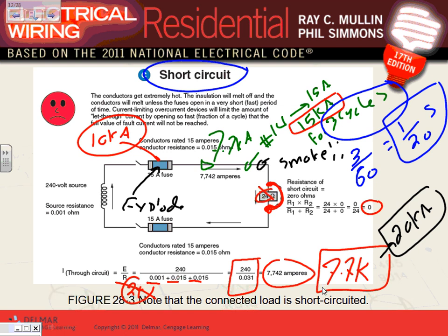It's still a fault. So the fault can be phase to phase, or phase to neutral, or phase to ground. What's the worst? The worst, guys, is usually phase to phase. If you have three phase, phase to phase to phase, bolted together, that's the worst scenario. Under certain circumstances with a generator, the ground fault can exceed the three phase. I don't want you to think of that, because we always limit the available short circuit to the three-phase condition, which is the worst scenario.